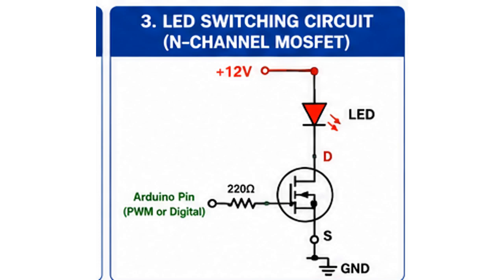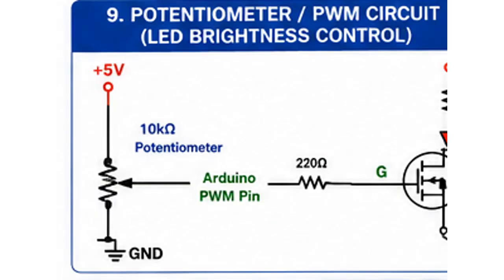Always remember that the physical pinout is not identical on every package. An IRFZ44N in a TO220 package has one arrangement, while a surface mount device may be completely different. Check the datasheet for the exact pin connections of the part you are using.